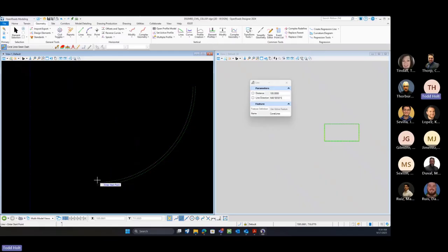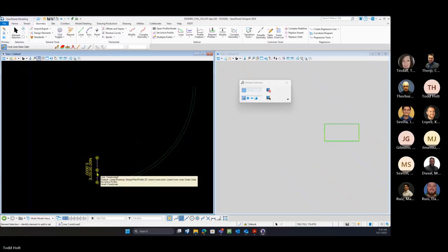So if I want to establish, from this curve back top, if we go 5 feet in distance at 90, I just want to establish where that distance or buffer zone is for our sidewalk. I'm going to place that line in here. If I click on this line now, with persistent snap off, it's not creating that little glyph or the rule.